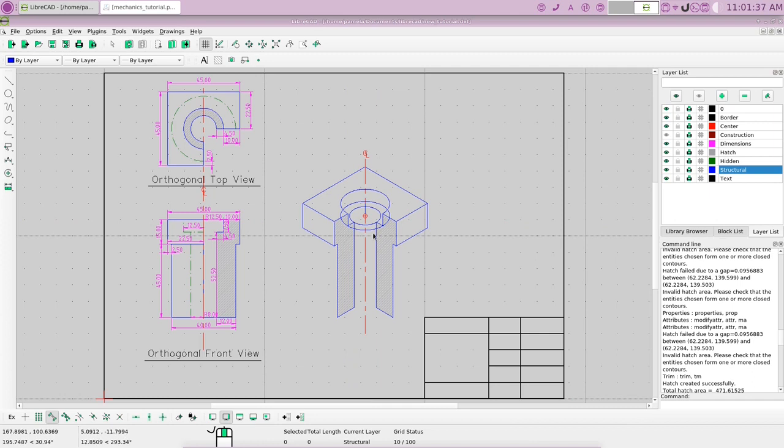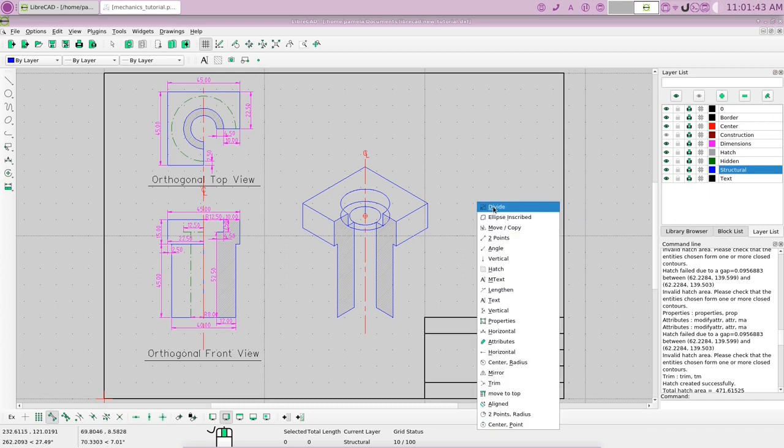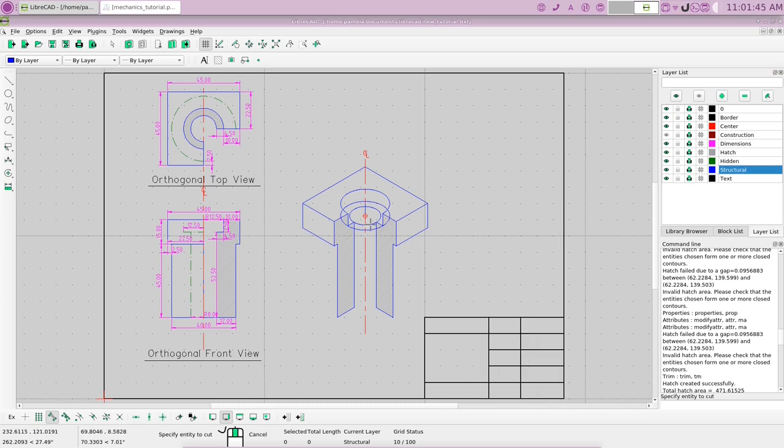Now let's look at these other ones here. Let's go back to the divide. Let's highlight the circle to divide, and on endpoint right at that line, select it again, and on endpoint at that line. Now highlight the piece we're going to remove, hit the delete key, it's gone. Now you can see we have this line here, this circle here.